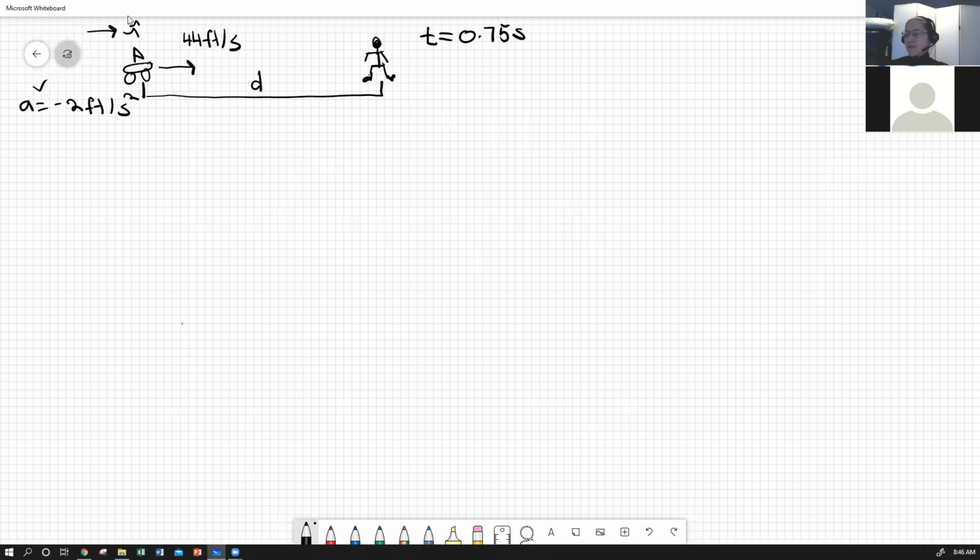So that's something else that's used in highway design: sight lines. It's used especially for maximum slopes. At what point in the curve and the hill, if you're coming up one side, will you be able to look ahead and see somebody that might be out of their lane, that's in your lane?